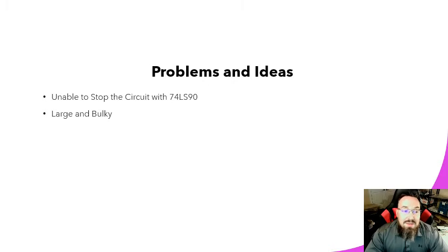Different problems and ideas that I had with this. One of the problems: something that was desirable for the circuit, I would have liked to have the circuit be able to stop after a time frame instead of resetting. I don't think that's possible with the 74LS90 since it's asynchronous. It'll just keep continuing to count down.